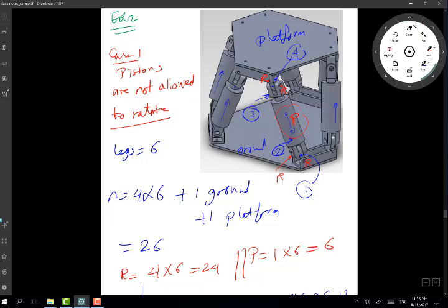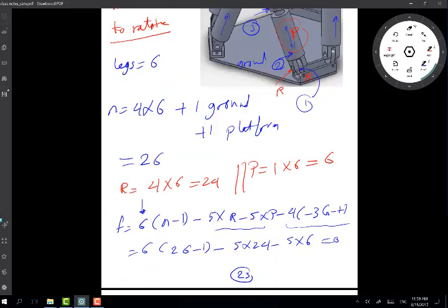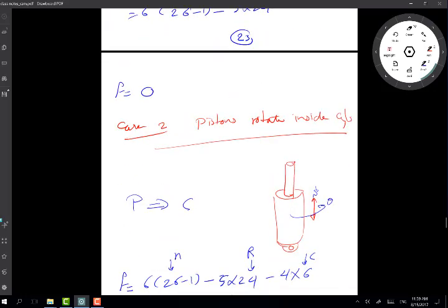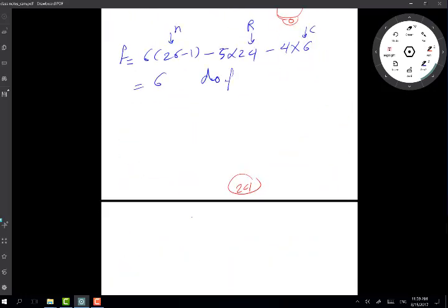The calculations are quite complex, because if you want to place the platform at a given position and orientation, you need to calculate all 6 motions corresponding to it, and then move those linear actuators to produce those motions.